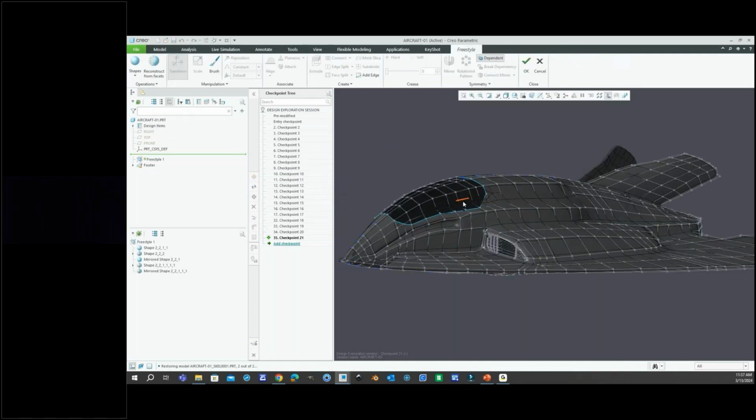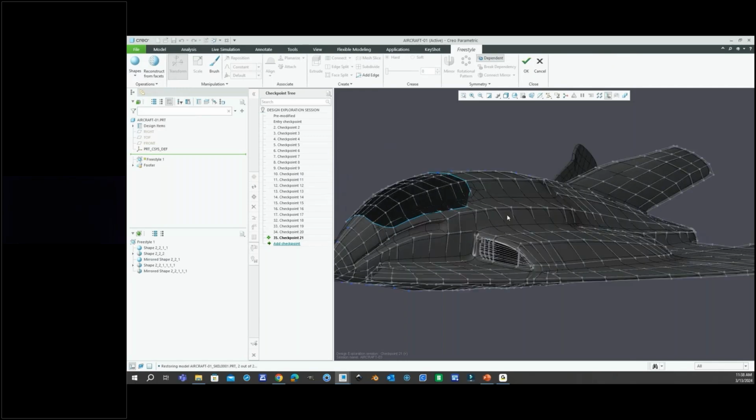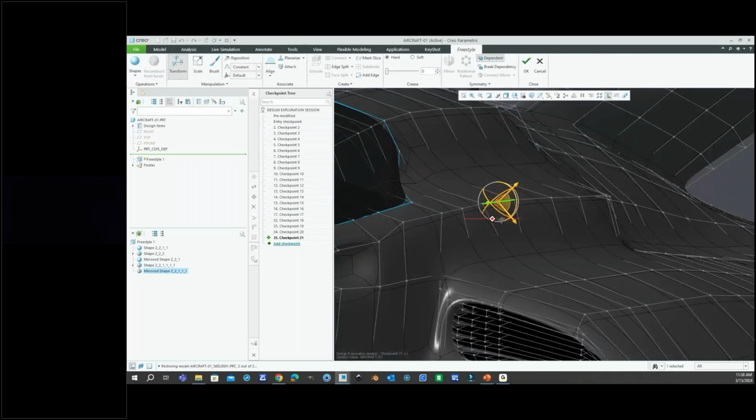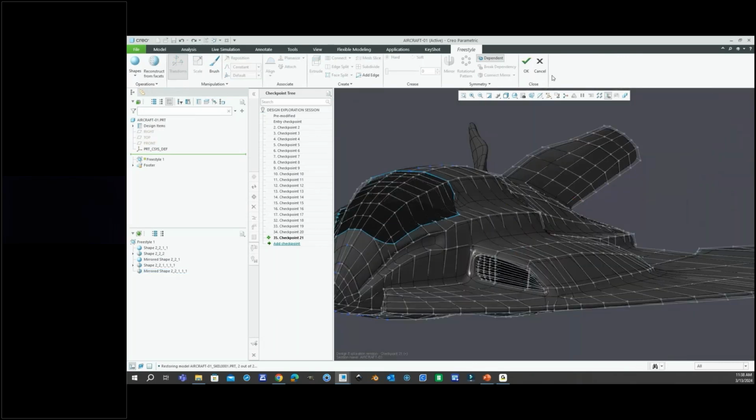Okay, and you can see that we have a bunch of points here along the mesh. To start with, you would basically go to the shapes group and bring in a primitive shape, like a sphere, for example. Then you begin to sculpt that. I can go in here and make changes if I want. I can grab that vertice, I can grab that edge or face, then pull that out and adjust that. So I'm not going to do that. I just wanted to spend a little bit of time on this so that if you're not keen to freestyle, you can take a look at it and kind of get a gist of what that is. All right, so let's cancel that.